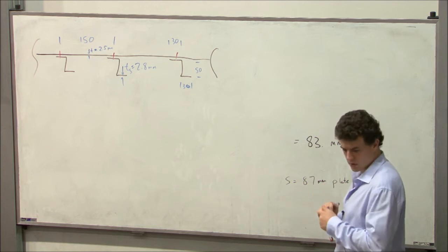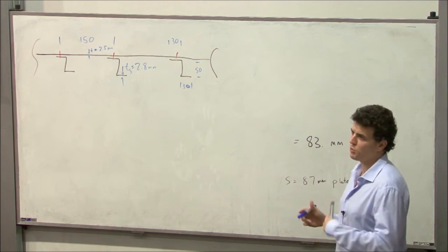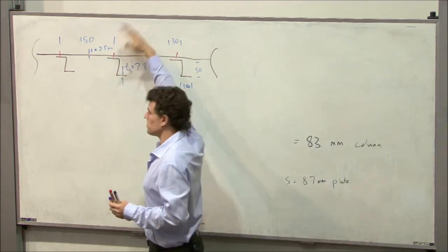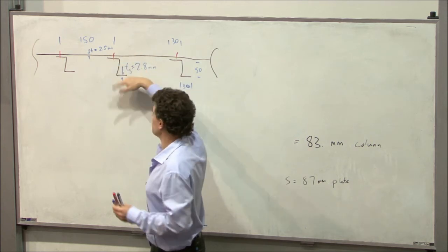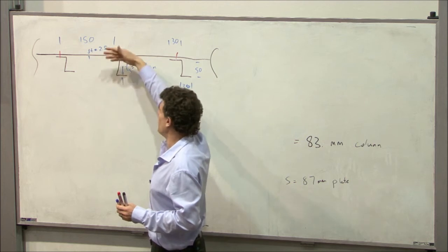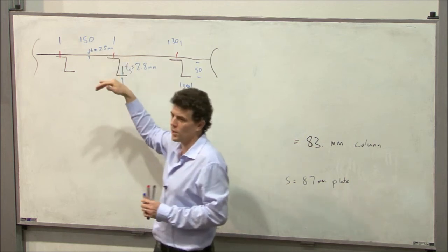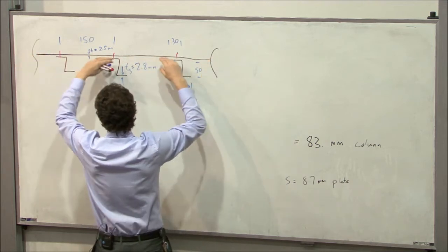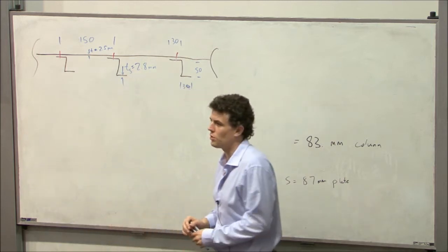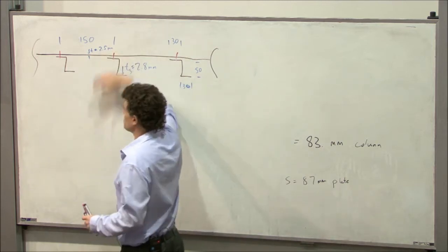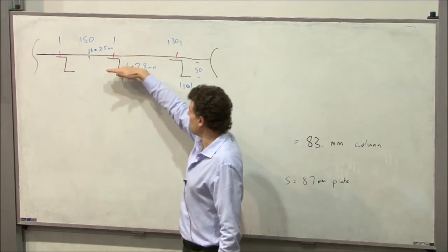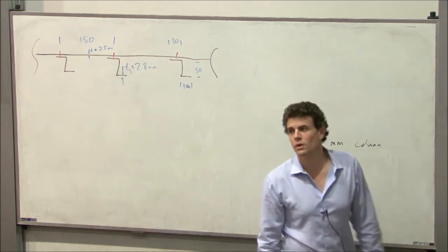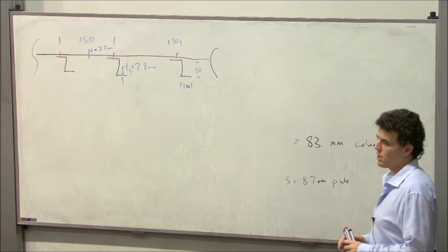Yeah, it has. Okay. So one of the simplifications that we make, and it's a fairly reasonable one, is that these will only ever buckle about an axis parallel to the board. So the buckling modes are just going up and down the board. We don't have to worry about buckling around other axes because the skin is still intact. Even though it's not carrying any extra load, it's still going to support any motion of the stiffeners laterally across the board. What it won't support is motion of the stiffeners up and down. So any bending as a result of the buckling will happen about an axis that's parallel with the skin. So that's the first simplification to make our life a bit easier.